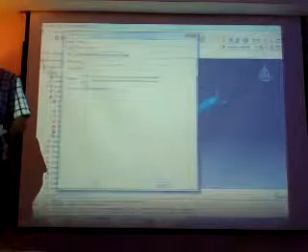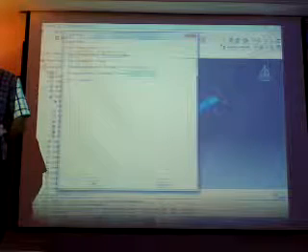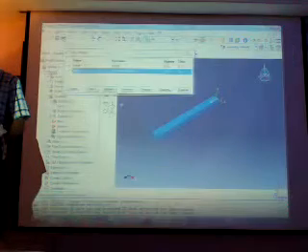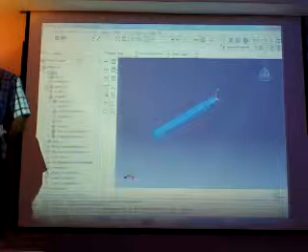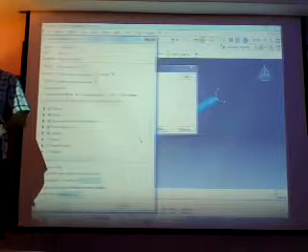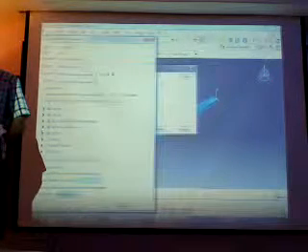Here, as a default, nlgeom is on, so our simulation will be non-linear. We have different options, incrementation, mass scaling, and other. We keep all of them as a default. It's okay. Now our step is dynamic, and static changed to the dynamic. Here, in the explicit, by default, we have 20 frames. We can change the number of the frames. Here you can see the interval is 20. As the professor said, I changed this one to 10 frames. The interval is 10.